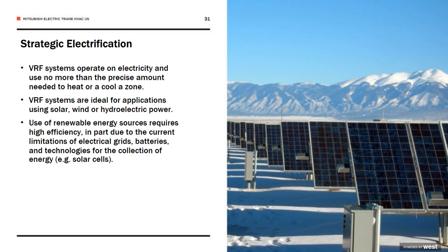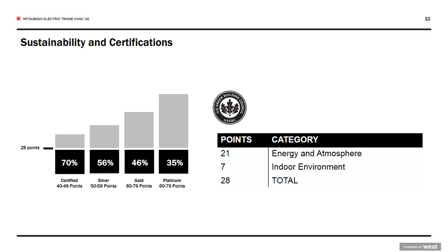It plays nice with solar, etc. From a sustainability perspective, if you design an HVAC system with VRF, you can earn a ton of LEED points. So as much as 70% of your LEED points can come from VRF if it's certified level, and you can earn up to 35 points if you're seeking platinum level.